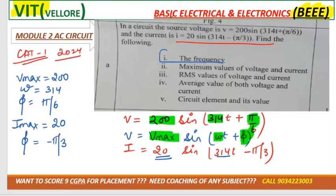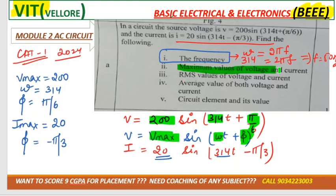Now let's see what they have asked. They asked you to calculate the frequency. So we know omega is equal to 2 pi f. Omega is 314, so 314 is equal to 2 pi f. So f is 314 divided by 2 pi, right? Pi is 3.14 only, so you will get the frequency as 50 hertz, right? In the next part they have asked the maximum value of voltage and current, which we already calculated by comparing the equation. Vmax is 200, Imax is 20, right?